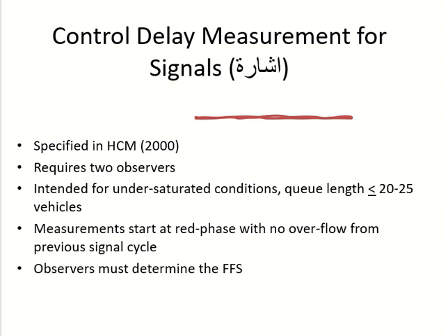How much is too long? This much. If the queue is longer than that, we should avoid doing the study in that time period. Clear? Another indication of the same thing is that we have an overflow. Overflow is also an indication that the queue is too long.